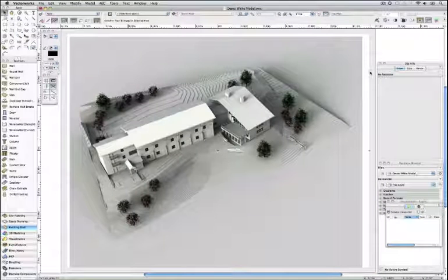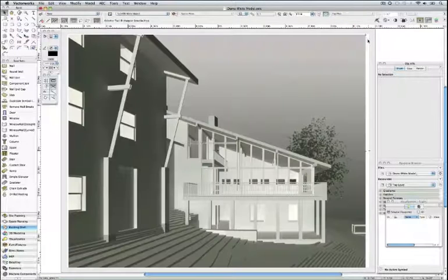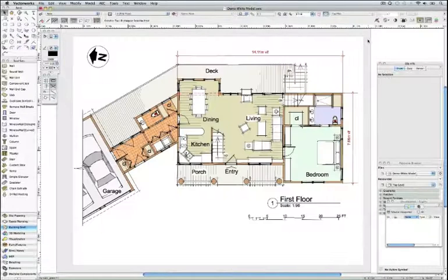Okay, so we'll switch up files again, and now we'll look at some rendering techniques using Renderworks 2011. This first tip involves a procedure we used during our presentation of some of the improvements in Renderworks. The results look as if someone took a photograph of a white or museum board model. White model renderings are just one more graphic technique that can help you explore your designs and clearly show your client the general massing of his project without getting hung up with color and texture.